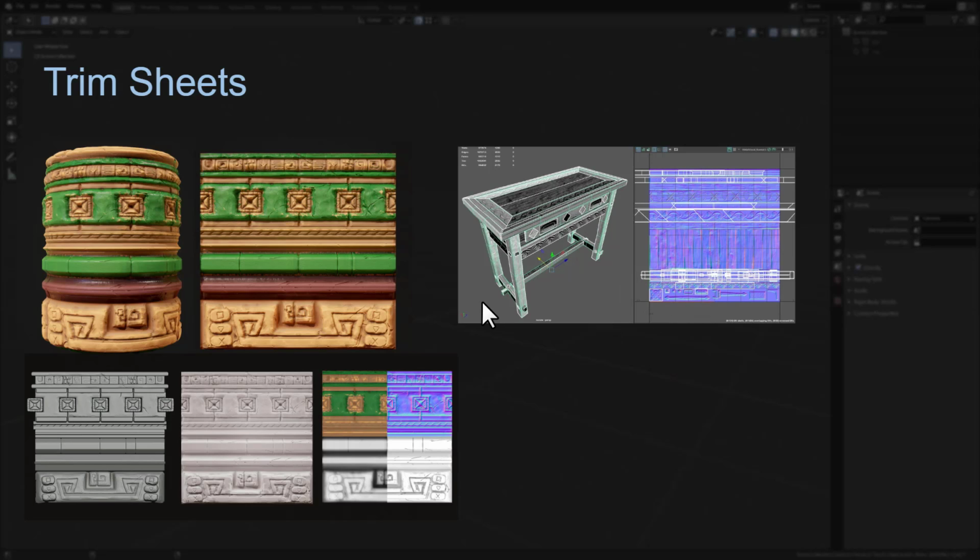This technique is very common in environment design workflows for games where an object has a set of consistent pattern details and get reused on the objects. It's become more and more common, and you can expect a wealth of tools and plugins to become available to help you lay out trims on a model. It does require you to be more precise about your edge flow and topology in a model, because you might need edges to repeat trims appropriately.